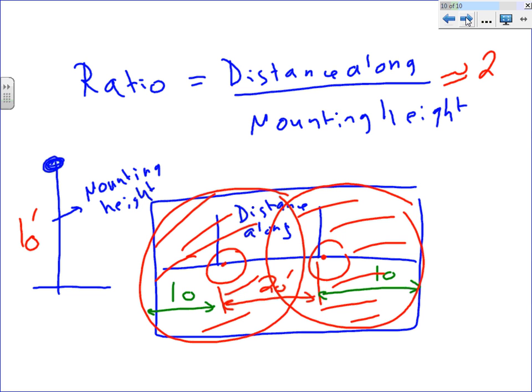Wow. And that's what scares me, guys, when we design a system and we add the maintenance factor. If you add a maintenance factor of 80%, this means you will have 20% extra light day one. That might be annoying for some people. 20% extra light than what you designed for on day one, because we want to accommodate the reduction of light in the future. So keep in mind, yes, you can put a maintenance factor of 0.75 just to cover your butt, basically, but be very careful. Day one, your light will be very bright, much brighter than what you thought it would be. So that might annoy some people.